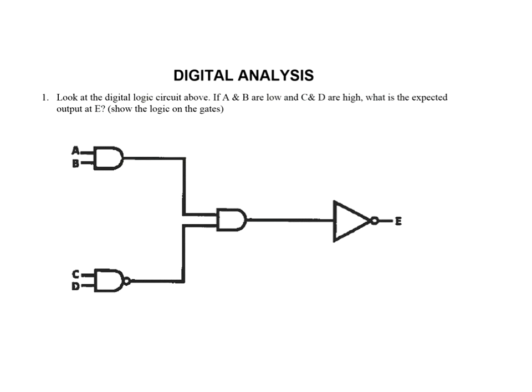Okay, you're going to see these kinds of things on the test. This is a very common diagram you'll probably see. First of all, when you look at this, when is the only time I'm going to get a high out of this? Well, what kind of gate is it? It's an AND gate, right? There's no NOT on the end. That's an AND gate, so both of these inputs have to be high for me to get a high out of this. So let's think about that.